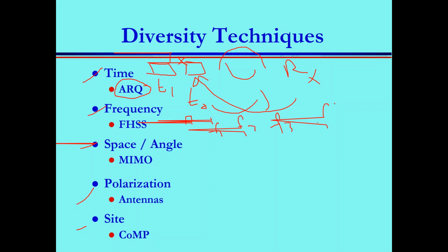We will talk about how to serve a million users with 2 megahertz bandwidth. Can you do this? This is a challenge in wireless systems because 2 megahertz, theoretically, can serve only 100 users. But your country has 20 million users. How can you serve them with 2 megahertz? This was extremely challenging at the time of the first digital wireless systems, GSM, the second generation we call it. Now we are at 5G and people are starting to work on 6G and preparing techniques for that.